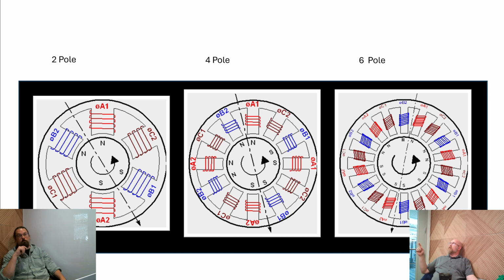And so that means that for it to go through one single cycle of rotation, it goes around only halfway. And remember the relationship between these poles, like the red pole, if we're looking at the center here: we've gone from an angular difference between 2 sets of poles of about 30 degrees to essentially 15 or 20 degrees, whatever that works out to.